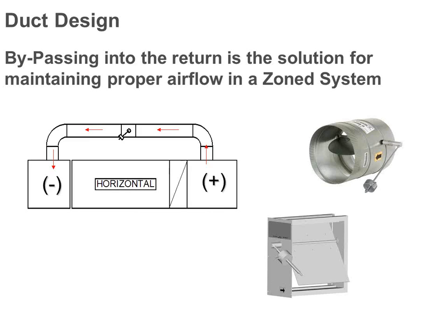Dick actually sends in a question asking if there's anything that should be considered when setting up a future zone, such as possibly a future basement finish out. Yeah, in general, whether you have zoning or not, if someone tells you, and you're helping them redo their ductwork in their house, that they might finish the basement 3, 4, 5 years down the road, I would design the ductwork for that specific scenario, right?